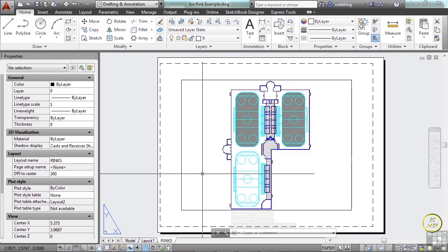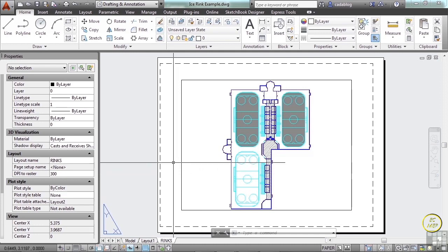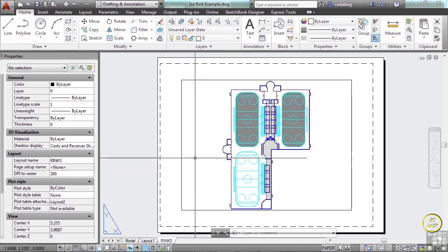When a new tab is made, a default viewport is always created. You can use that one if you'd like, or you can create one from scratch. We're going to use this one, but then we'll make an additional viewport later on, because you can make many different viewports. A viewport is an object just like anything else. It can be moved, copied, deleted, rotated, etc. Let's move this one right now.